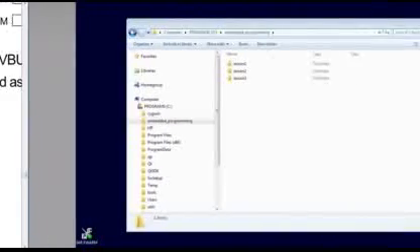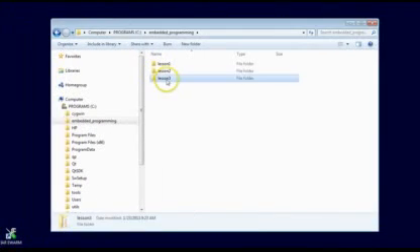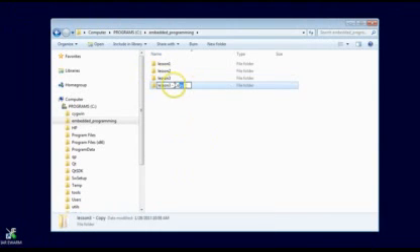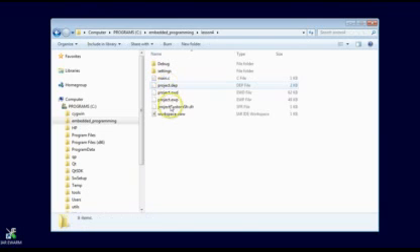So now that you have some idea how the LED is connected, let's prepare the IAR project for this lesson. As usual, let's start with making a copy of the previous Lesson 3 project and renaming it to Lesson 4. If you don't have the Lesson 3 project, you can get it online from statemachine.com/quickstart. Get inside the new Lesson 4 directory and double-click on the workspace file to open the IAR toolset.